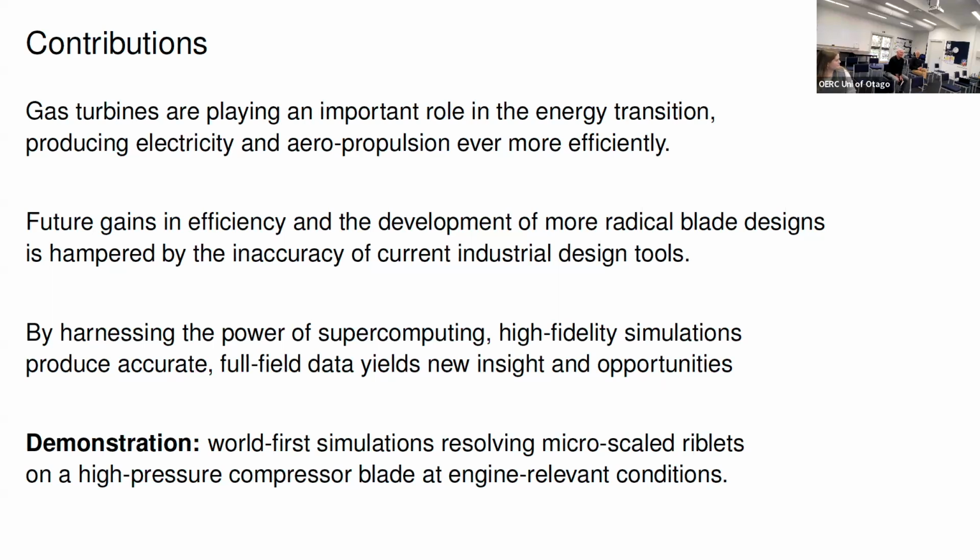I represent a company that has developed a small-scale wind turbine. It has a 1.8 metre long blade, and we've aimed our Reynolds numbers at between 600,000 and 700,000. We've got a pretty strong interest because the machine is stall controlled, exactly where that separation happens, and making it consistent. We've had some bad results from inconsistent stall initiation, and I'm very interested in this idea of ruffling the surface in some way to make that stall point